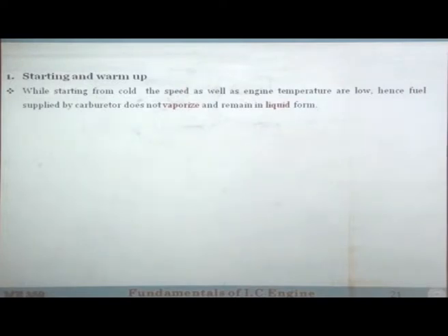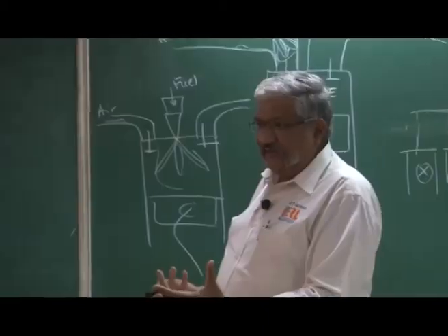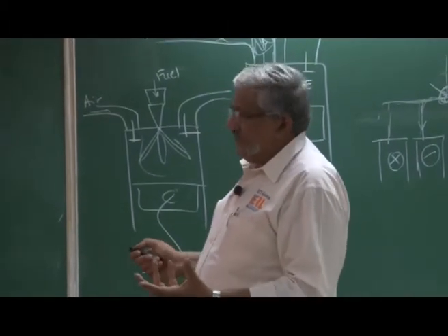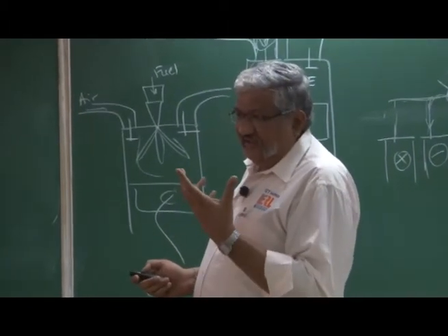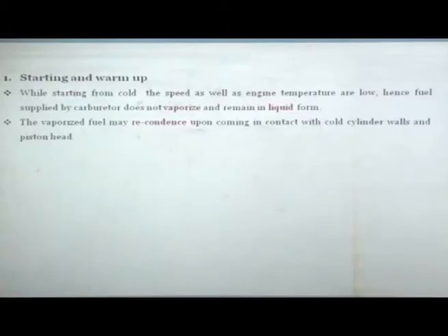And obviously there will be injection, because the moment you start cranking, there will be vacuum, and because of the vacuum there will be suction, and because of the suction the fuel will be injected, but it will not vaporize. So, there will be a lot of fuel which will stay in the manifold in liquid form. Okay. And if some fuel has vaporized by any chance, there is a possibility of recondensing. Okay.